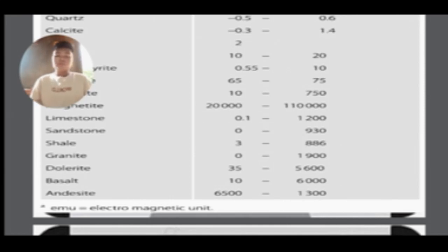The effectiveness of the magnetometer survey may be hampered by local magnetic disturbances, which could result from buried or overhead live electrical cables, buried pipes, wire fences, and so forth. So there is almost no chance of conducting an effective survey in an urban area. So, no chance at all.